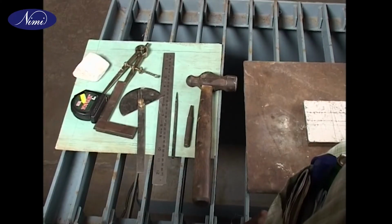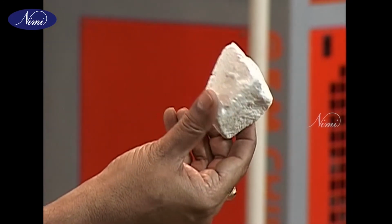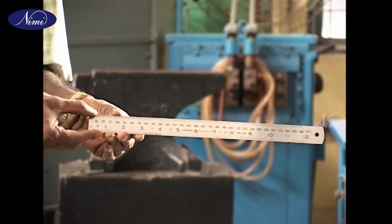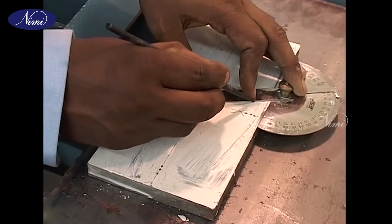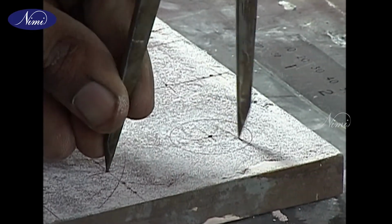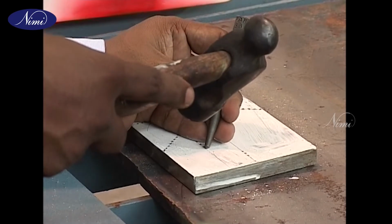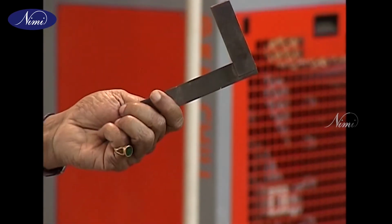Various tools for marking and layout of the job are displayed here. This chalk block is rubbed on the surface of the plate to be marked. This is a steel ruler with scales in inches and centimeters. This is a bevel protractor used for marking bevel and inclined lines. Wing compass used for drawing circles, arcs and also for marking equal lengths on a line. This is a center punch used for marking punch marks on a line. This is a tri-square for marking a perpendicular line to another line.